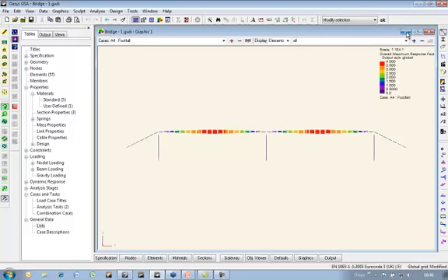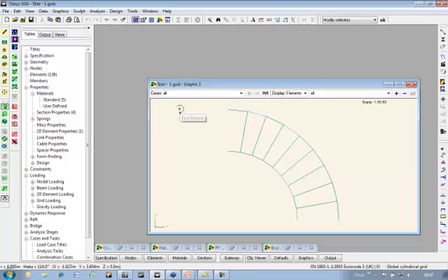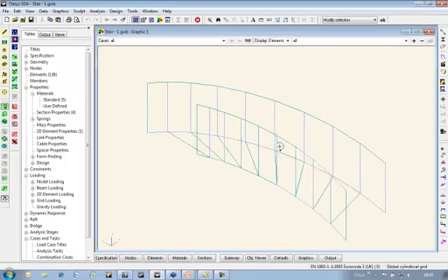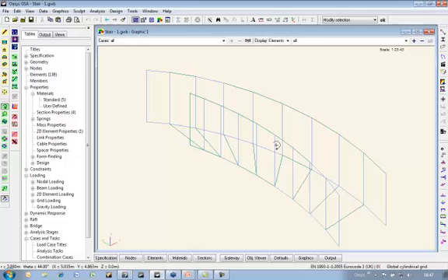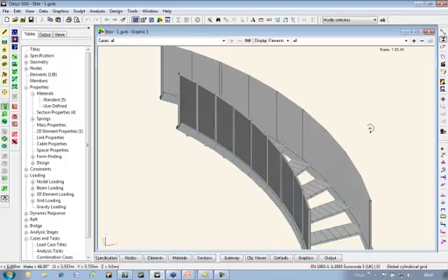I also mentioned we can do staircases. Now staircases have the problem that, one, they are very, very light, and secondly, that when people are walking up and down stairs, the impact forces are much higher and they're walking faster as well. Now this is a staircase model. There's no cladding on this, but obviously the balustrading can have an effect on the vibration of a staircase.